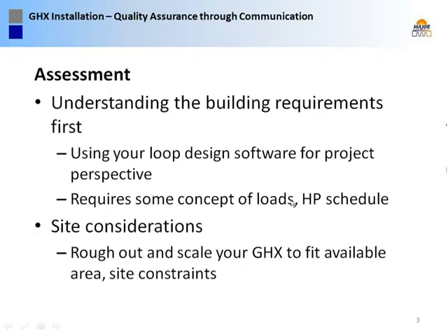I would like to make the point that what we find is a big help on any project is a preliminary assessment. It's not just looking at the site, but before you actually get going, understanding the building requirements first. That is, before you start playing with your loop design software, you have to understand your loads and your heat pump schedule first. Then you have to look at your site considerations, and then you can use GLD or any other appropriate loop design software to try and rough out the size and scope of your loop field.